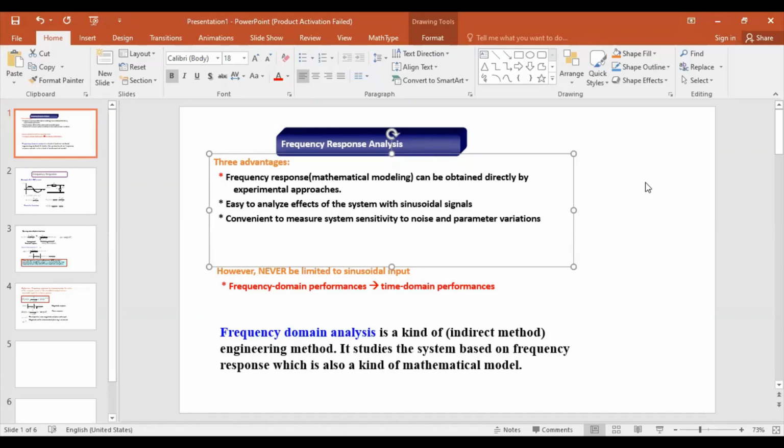So that is one beauty of frequency domain analysis. If you have a signal which is a combination of different signals, you decompose them in the frequency domain and process each and every signal at a time, then add the responses of all those individual signals to get the total response. So I hope it is making sense to you.